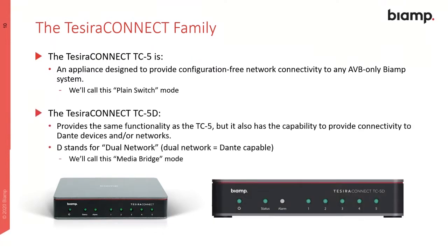The other version, which we call the media bridge, is the TesiraCONNECT 5D. Dante is a well-known protocol in the market, and most third-party devices will have the Dante protocol. So we provide the TC5D, which can give you a nice connectivity tool. You can connect with any Dante system through the TesiraCONNECT D. The D stands for dual network, so it accepts Dante. That's why we call it media bridge.